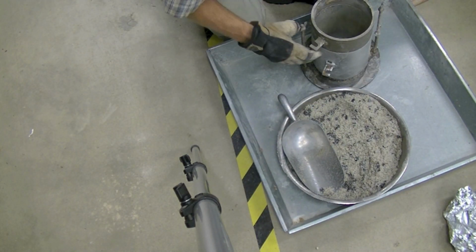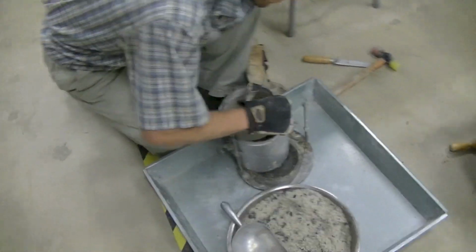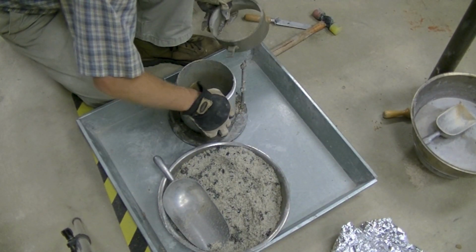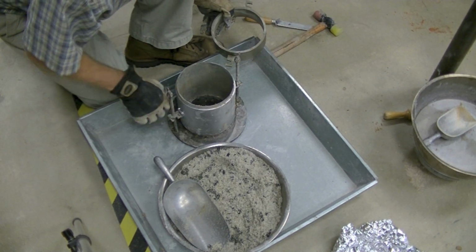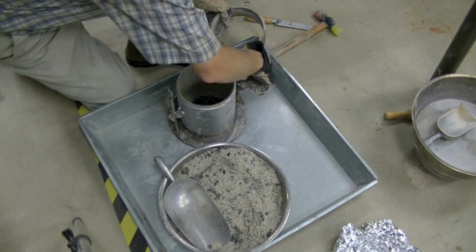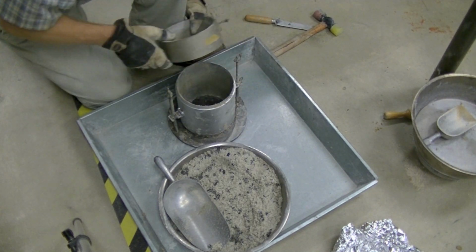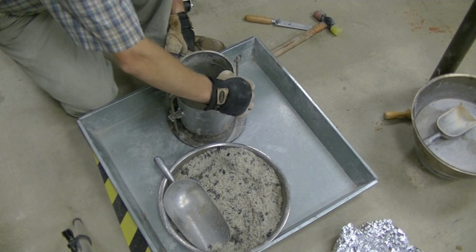Here's an aggregate base course sample. It is considered crusher run or crushed aggregate. This type of material is mainly used directly beneath large-scale roadways with an asphalt or concrete covering. Here method C will be used since the gradation requirement for method B was not met and approximately 23% of the material by mass was retained on a 3/4 sieve.